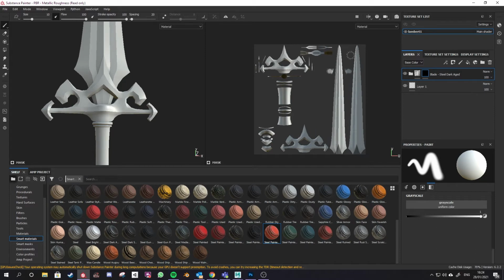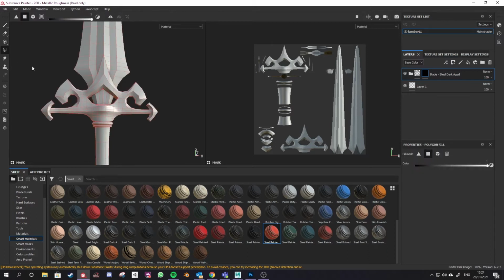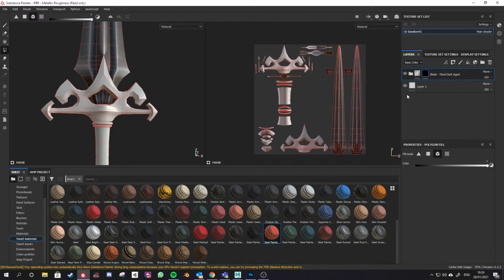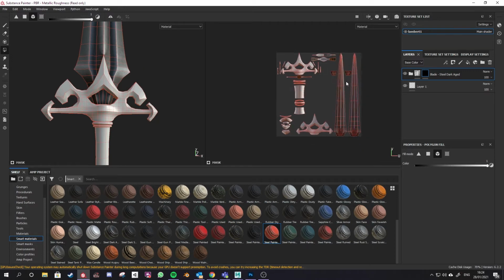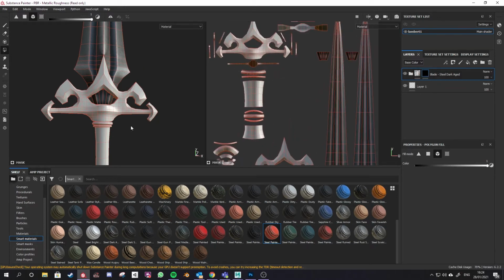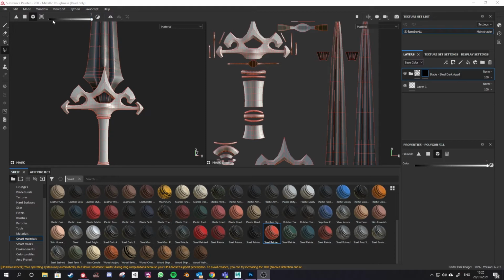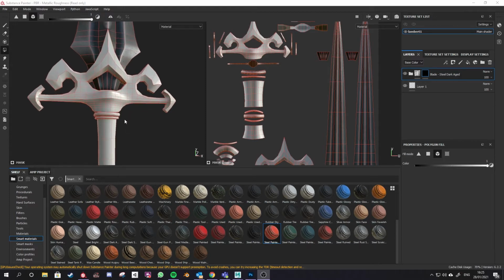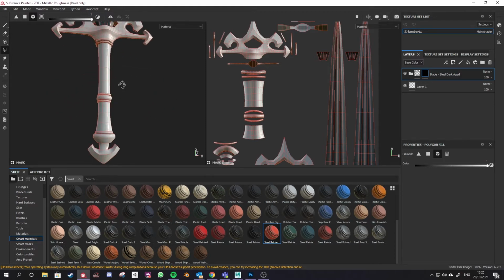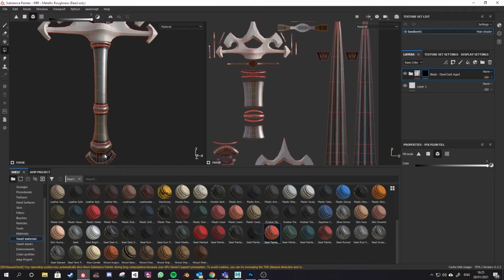Now we want to just coat the blade, so we're going to go down to this little selection, Polygon Fill. It's the fourth tool down in the toolbar on the left. I'm going to select that, and you see here we can select our triangles, polygons, meshes, or UV chunks. So I'm going to try mesh here, and then I'm going to click on the blade, and you see that that entire mesh, everything that's attached to those faces, will now get coloured in the map. So for this tool, we can use either the 2D map or the 3D map to apply those things. And all that's doing is painting bits and pieces of the map out, depending on what's attached to what.